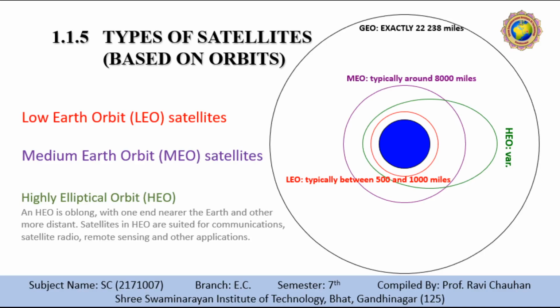Using advanced compression schemes, a transmission rate of about 2400 bits per second can be enough for voice communication. LEOs even provide this bandwidth for mobile transmitters, which have an omnidirectional antenna using low transmit power in the range of 1 watt. The delay for packets delivered via LEO is relatively low, approximately 10 milliseconds. The delay is comparable to long distance wired connections, about 5 to 10 milliseconds.